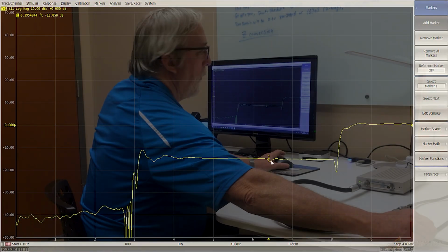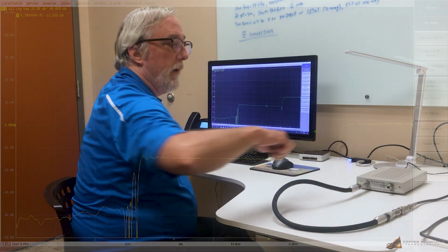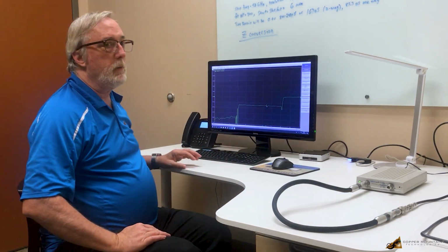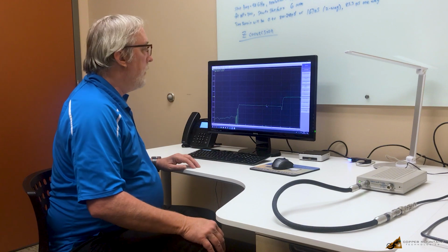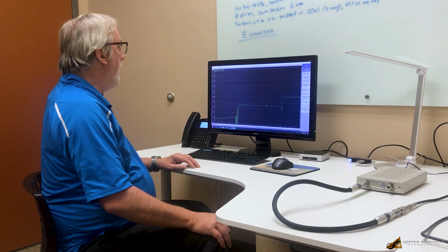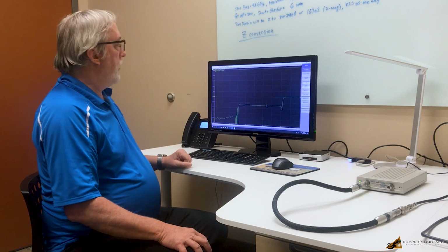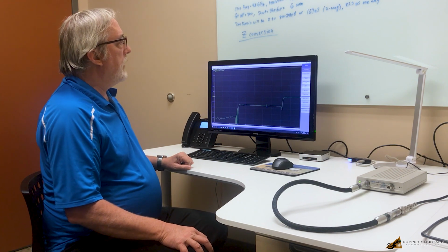It is 6.4 feet down this entire cable system. So it would make it very easy to find if it were a defect in a cable, say in a wall or some other hard to get to place. So I've demonstrated how to show return loss over distance. Let's do one more thing.